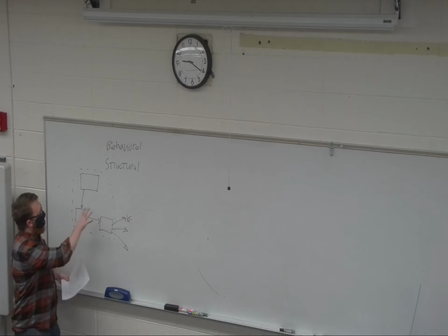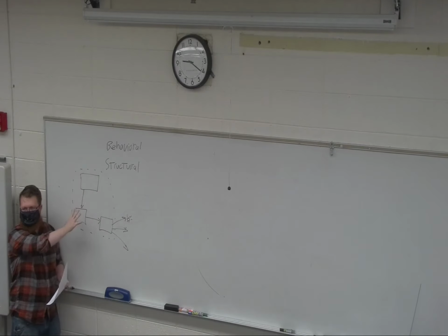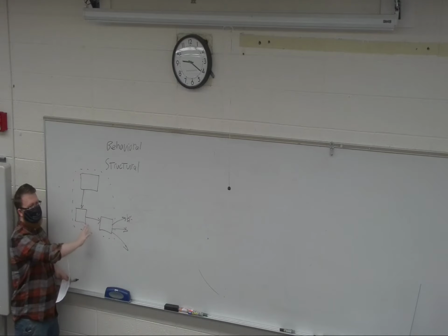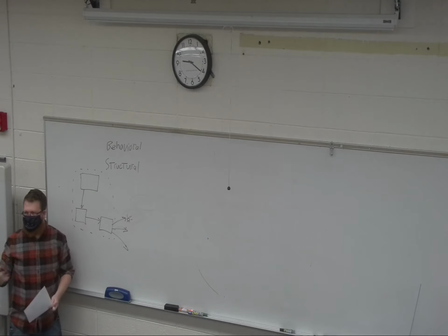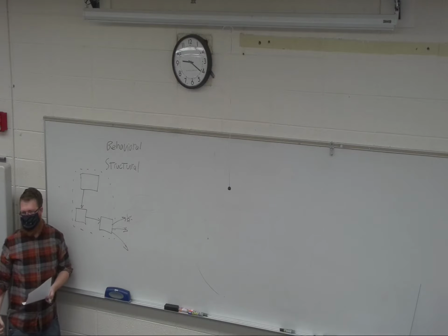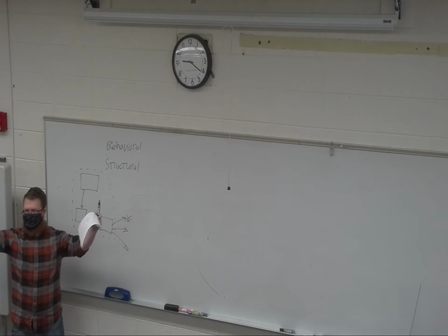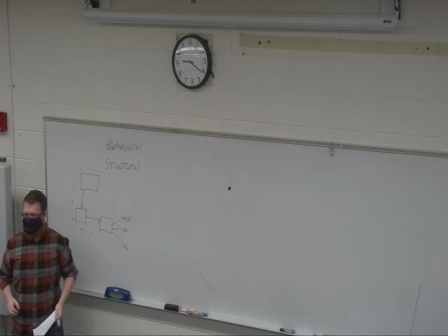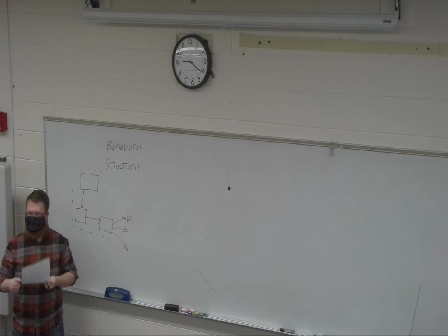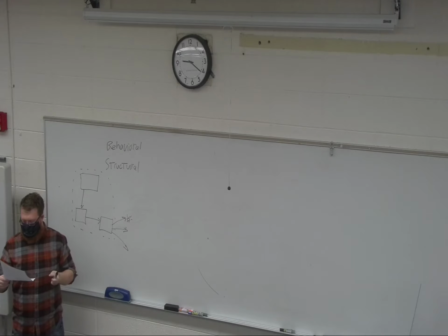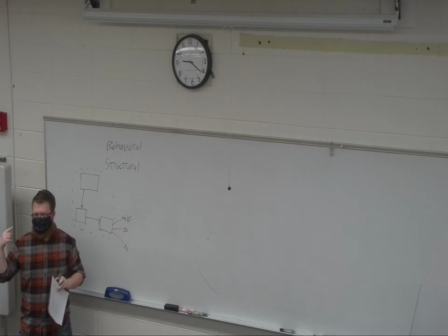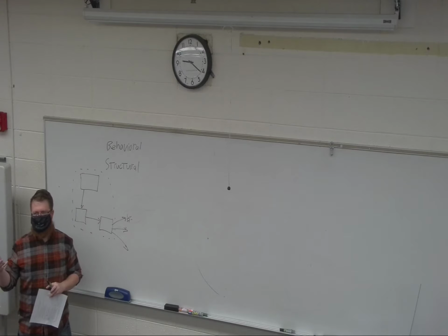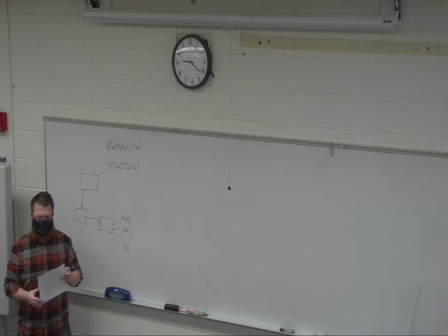But because of this structure of VHDL, where you get behavioral models tied together with structural, VHDL really lends itself towards what we call top-down design, which is where you start with these block diagrams and then you design inwards, essentially building more and more specific blocks as you go. There are other languages, of course, for hardware description. There's Verilog. Someone's made a Python that is meant for hardware, and there's also a C# version now, I believe. And I think there are two or three others that have been used.